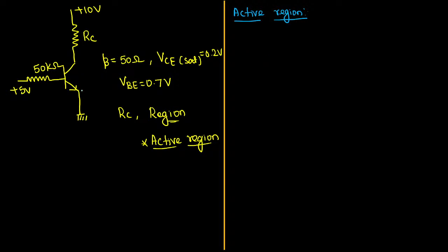See, it is an NPN transistor first. NPN means at the collector, current will be entering, at the base, current will be entering, at the emitter, current will be leaving. Then base to emitter voltage is 0.7, yes, it is given. Now here the current entering point is plus, leaving point is minus. How will you write down this voltage source? Positive plate is connected with the circuit, negative plate will be connected with the ground, that's all. If the positive plate is given at the supply, then automatically the negative plate will be at ground.